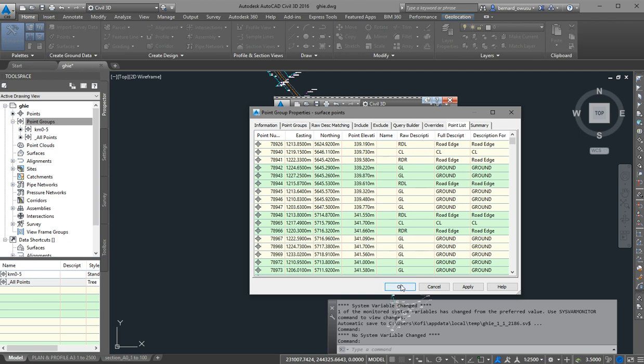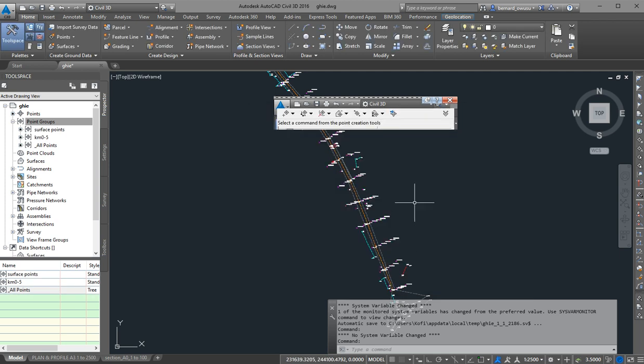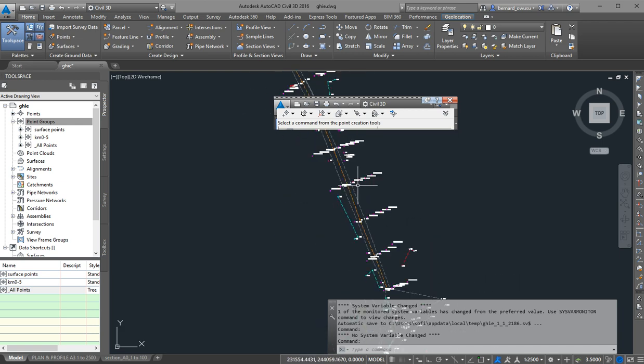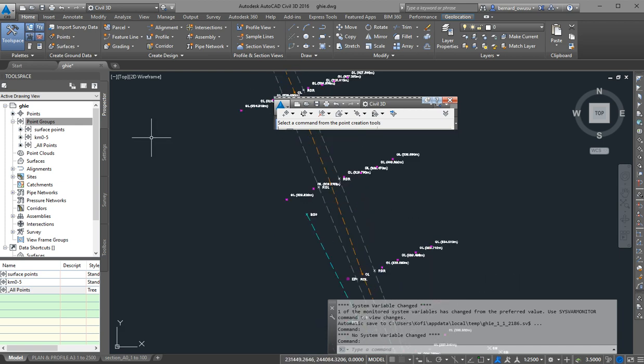So now you can please click on OK. Have we clicked on OK? Yes. Okay. Now we are going to create our surface. We have our surface data, or the points that we need to create our surface. Now, if you look under Prospector, after points, there's point group, then the next is what? Surfaces. There's point cloud, there's surfaces. We are going to use surfaces.